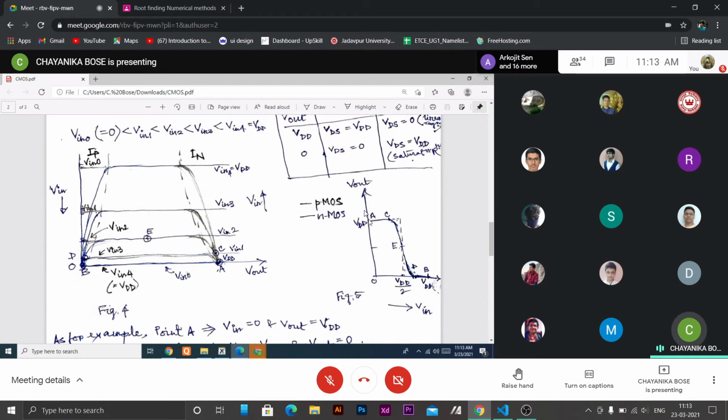That is the main criterion for digital circuits. This noise margin makes them robust. Now, for 0 volt up to 4 volt input voltage, the output remains constant. So we will say that this unit can handle a maximum noise voltage of 4 volt, and the output will be maintained.